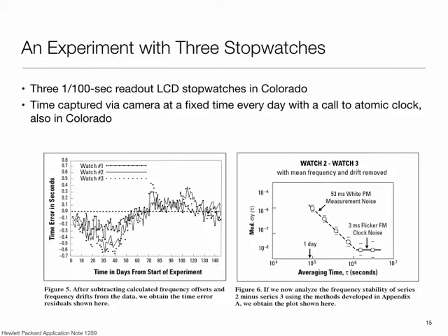The problem with the strategy is that you are calculating how many ticks you need based upon an assumption about the clock frequency. And so you have a few sources of error there. Number one, that assumption immediately raises the question, what frequency are you going to use? There is a nominal frequency that the clock hardware has, which, as I talked about, depends upon manufacturing variation. So usually what would happen is that by comparing against a time server using, let's say, the NTP protocol, you would have learned the frequency which you are seeing currently. So you have a better estimate of the frequency, which is the frequency right now.